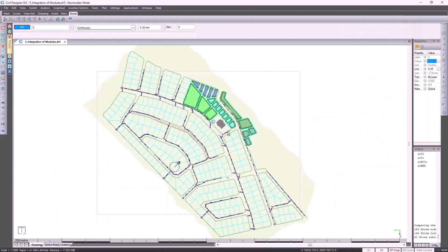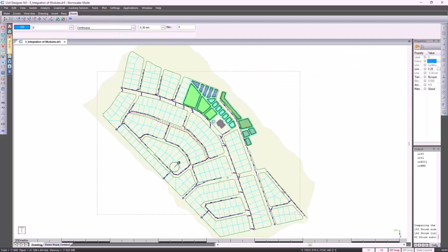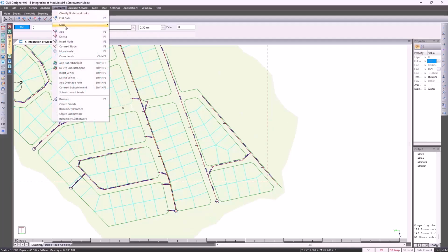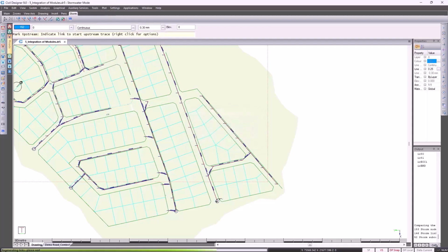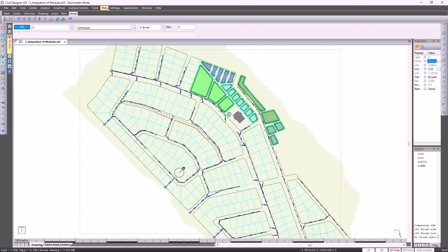If you've got other services associated to your project, you can go to Auxiliary Services and check for clashes. When looking at plotting, you could either plot the entire network or you could select portions of the network. In that case, you'd go to Graphical, mark everything upstream, select a manhole, everything upstream of that manhole will be highlighted, right click and quit, and then go to Plot, Generate.